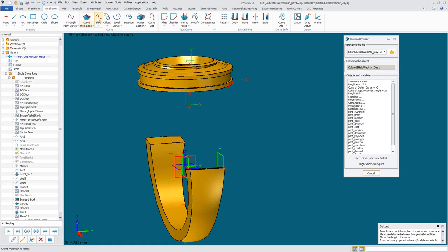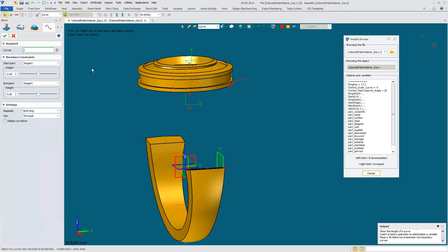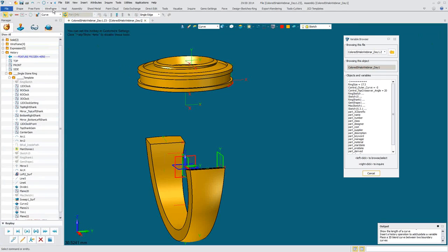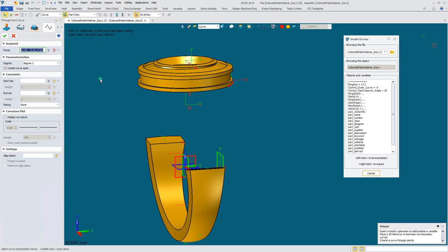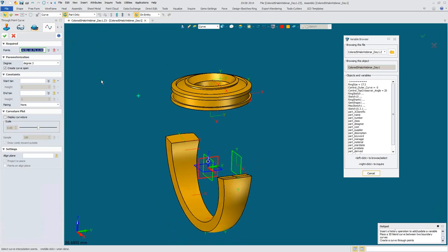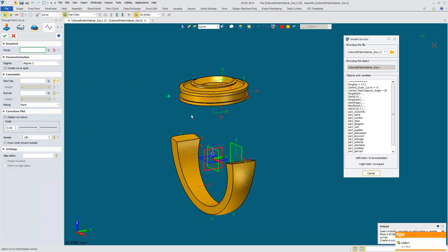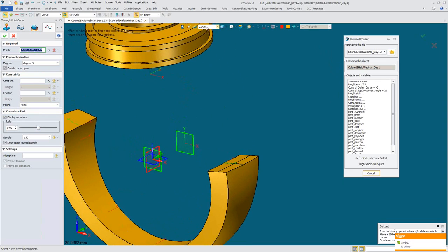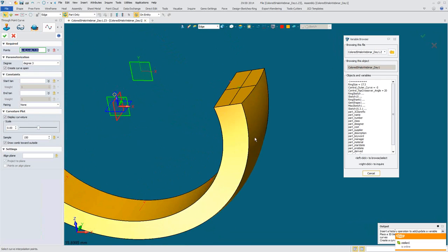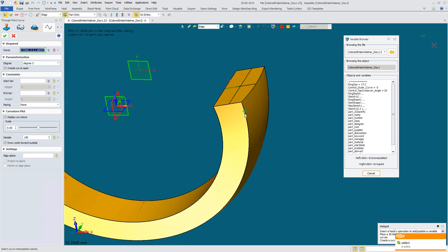All right. I was thinking of the blend tool possibly, but I see more controls for us in the wireframe. Through point curve tool. And I would like for you to see the display curvature. You don't have to work with this. I'm going to pick my points. My first point is off of the edge, this edge. It's important that we get this edge, all right?